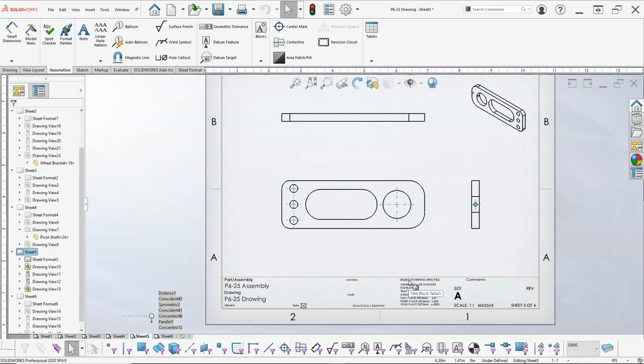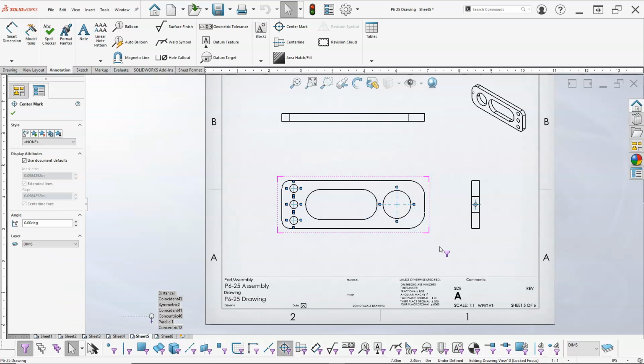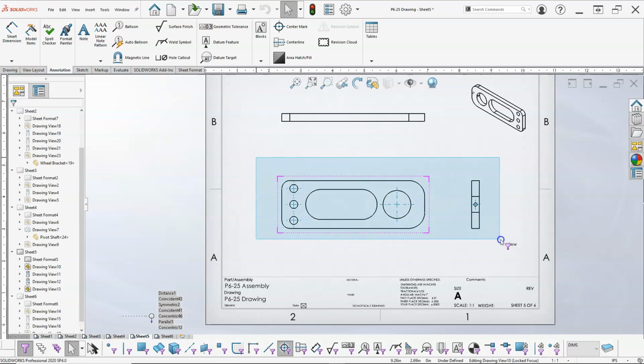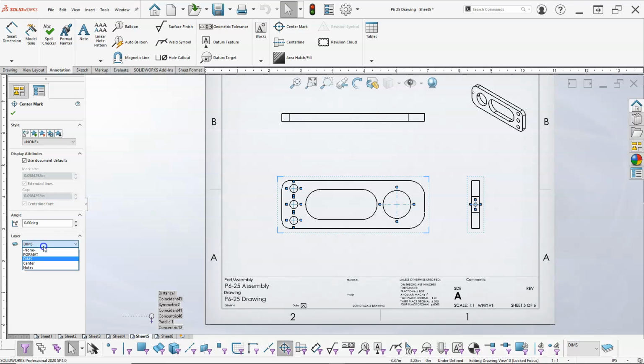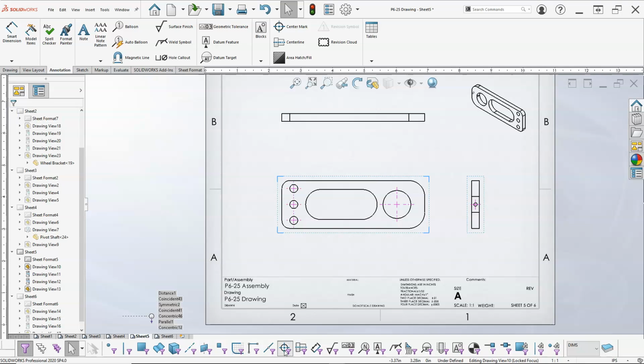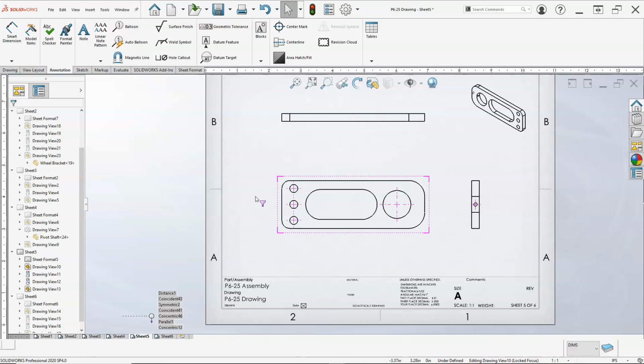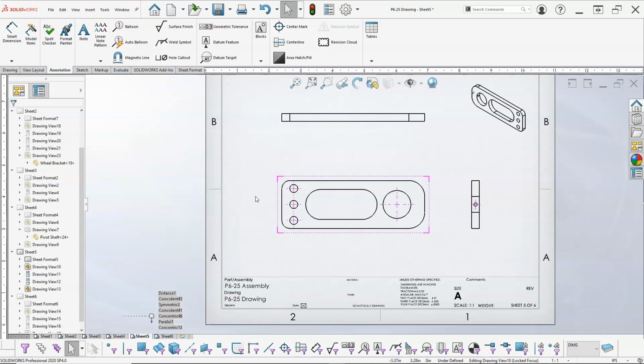And then I think I might be able to get all of the center lines. Picked up some stuff in the view. So if I come down to the filters and I grab my center lines, or center marks and center, then those will pick. We'll flip those over to center, and then I'll make sure. Now this is where F5 and F6 have always given me a little bit of a problem. F5 turns the toolbar on and off. F6 toggles the filter on and off.